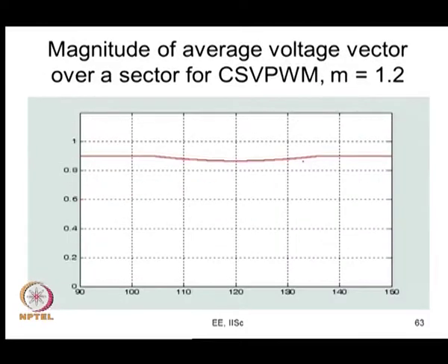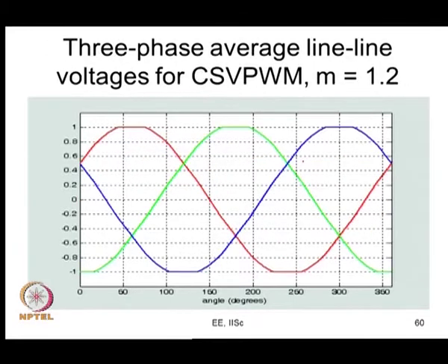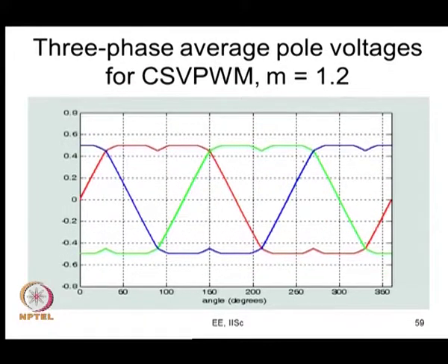If you go back, you will see that there are some places here, for example, where only one phase switches, only Y phase switches, whereas R and B are clamped. So, this is a case where only the active vector is switching, and in this case there is no 0 vector applied and the average vector tip will be touching the hexagon.